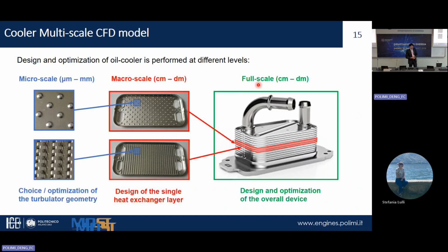So speaking of which, what we have next to this is the cooling unit. The cooling unit is usually made up of an ensemble of cooling plates, with two fluids. One is the dielectric oil, basically, and the other one is the cooling water plus glycol.